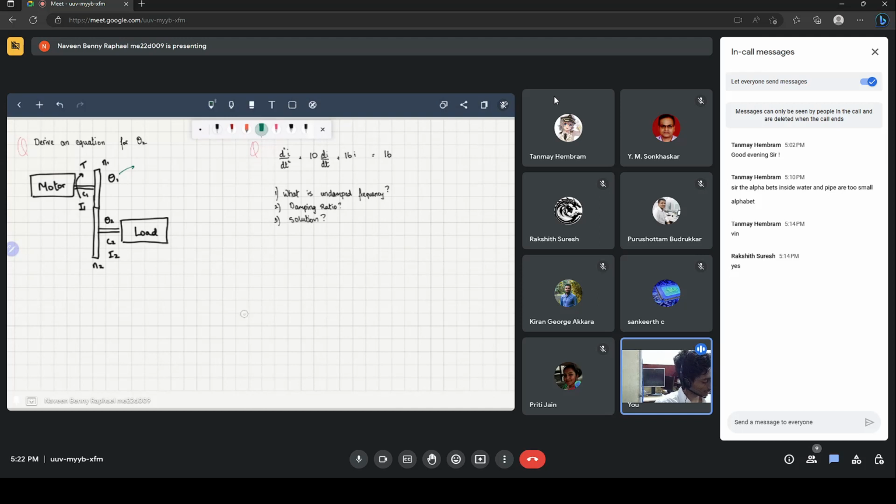So when you're solving this, naturally the first part is to write the equation, so let's consider the first gear. The first gear has two torques acting on it, the torque from the motor and the torque from the other gear. We know that every force has an equal and opposite reaction. Thank you, Newton, for that. So that means the force at this boundary has to be equal and opposite.